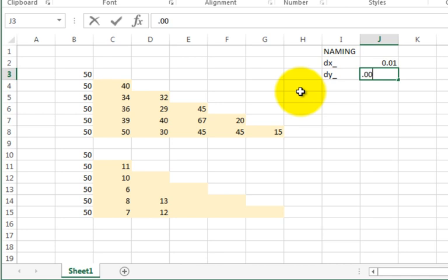All right, what was this one? 2 millimeters. Now we can put in our conductivity. What was our conductivity? 50? No, 25. I'm not going to put in the units, though I'd typically put in units. Convection coefficient. What was the convection coefficient? That was 50. Okay. Base temperature, TB. Probably TB underscore. T infinity. That's not infinity, so TINF. T infinity was 20, and base was 50. Okay.